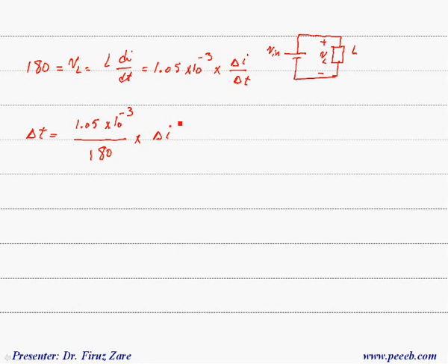Basically the latching current should be considered in this equation, because when we apply gate signal and turn on the thyristor, then the current through the thyristor and through the inductor is increased. So basically this is delta I, if this is current waveform.